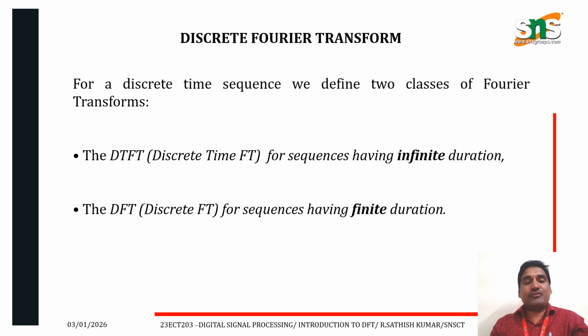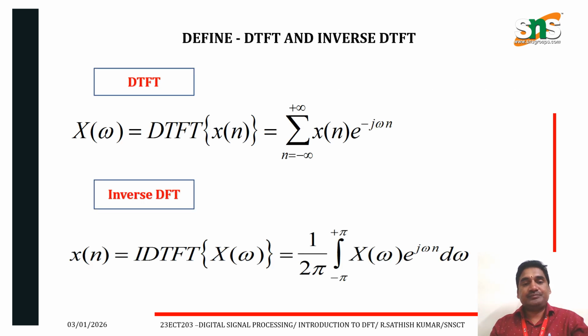Next one, discrete Fourier transform. For a discrete time sequence, we have defined two classes of Fourier transforms: the discrete time Fourier transform and the discrete Fourier transform. The discrete time Fourier transform has infinite duration. The discrete Fourier transform has finite duration.